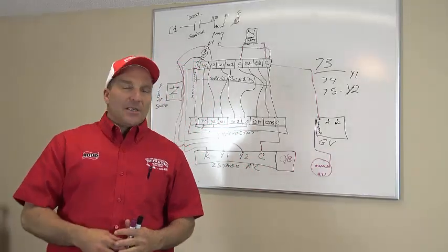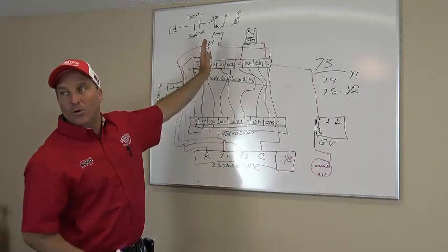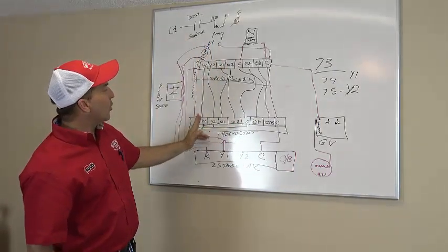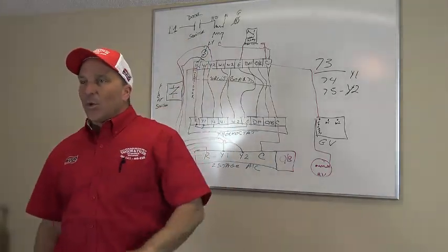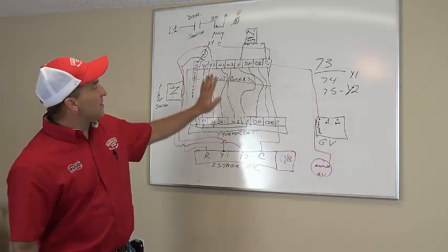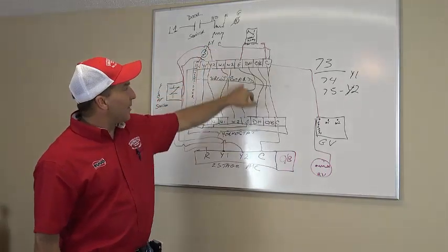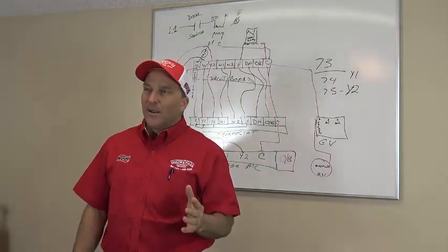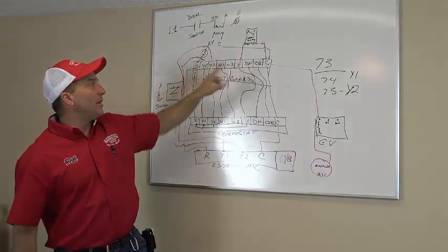So what I would do is I do not hook my Y2, because there is no Y2 on my circuit board. I only hook up Y1. And from my thermostat, I hook Y1 straight to my Y1 on my condenser. So when Y1 energizes, it bypasses my circuit board here, but it energizes my G on my circuit board. So as far as the thermostat is concerned, I'm energizing Y1 and G, but as far as my circuit board is concerned, I'm only energizing G.